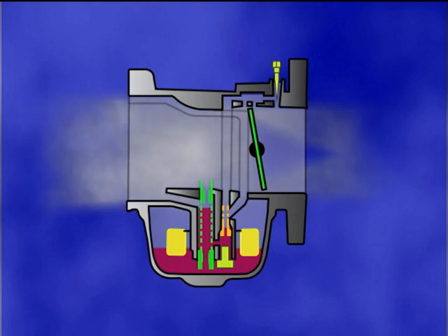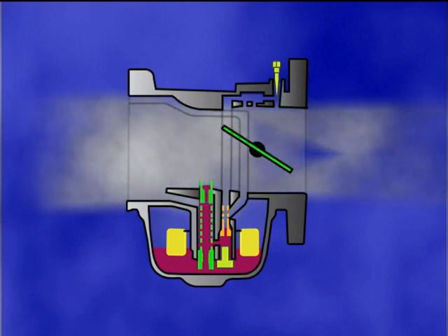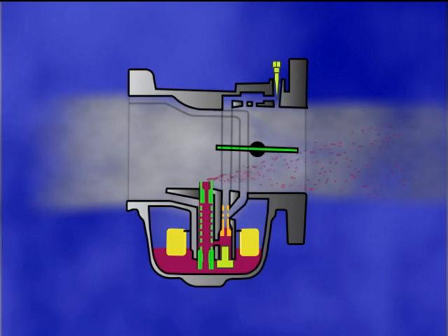The bleeder tube mixes the fuel with air from the main jet air passage. This produces an air-fuel mixture. As the throttle plate is opened, engine speed increases because of bypass circuit operation. At the same time, vacuum increases in the venturi. When vacuum increases to a certain point, the air-fuel mixture begins to discharge through the main fuel nozzle. The air-fuel ratio for the main circuit is controlled by the main jet size.